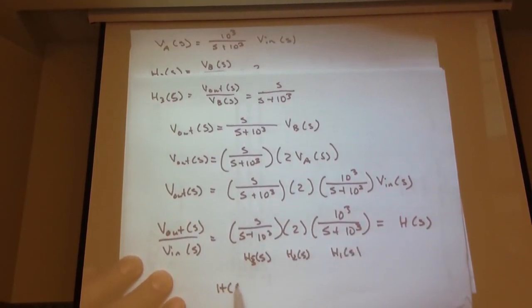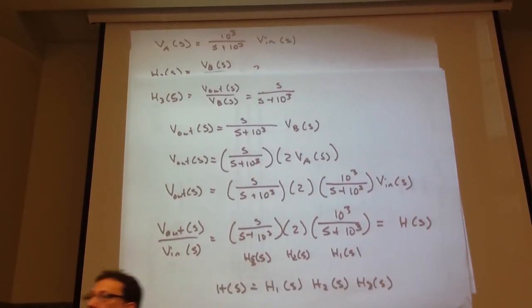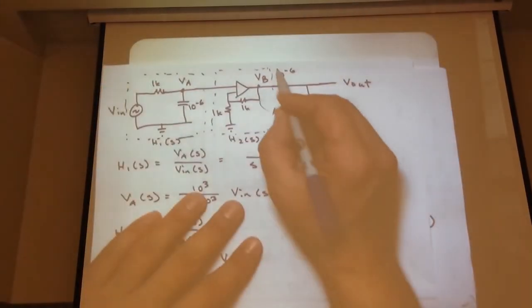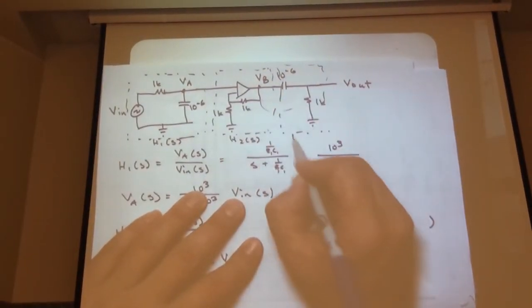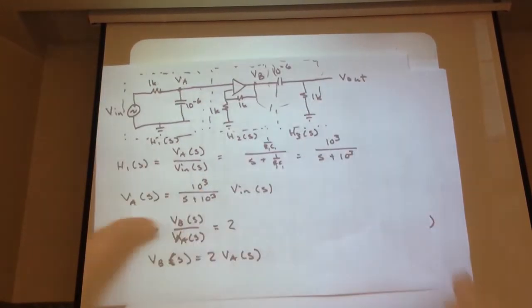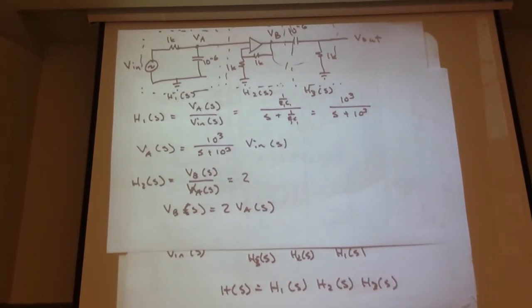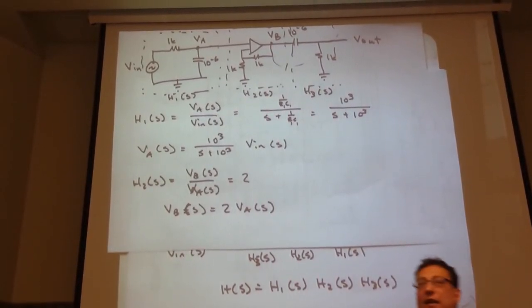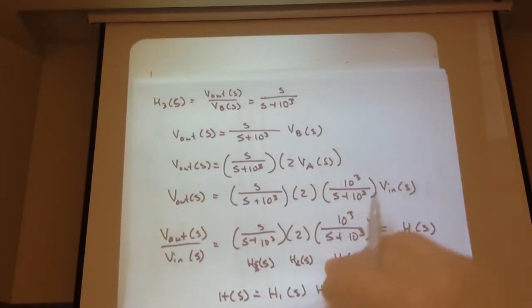And so, we can write this out using the parts for each isolated stage. The final transfer function is the product of the individual transfer functions. This is a 3-stage network. You can add a little H3 in here. This is a 3-stage network, meaning the output of each stage is independent of the next stage. And that brings up 2-port models.